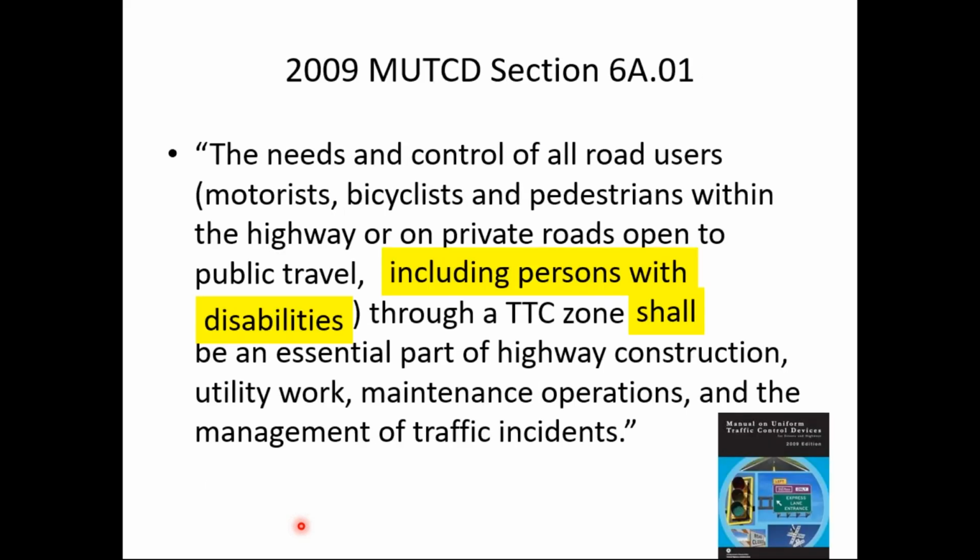And of course, those of you familiar with Part 6 of the MUTCD are very familiar with this language. We have to consider all road users, including pedestrians, but also, I highlighted, including pedestrians with disabilities, and then the word shall there. Shall be an essential part. So that's not just something that's nice to do. It's a mandatory condition under the MUTCD. So we have to accommodate those with disabilities.